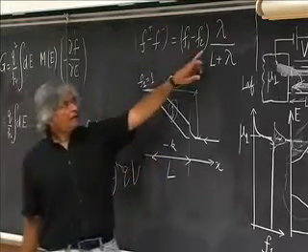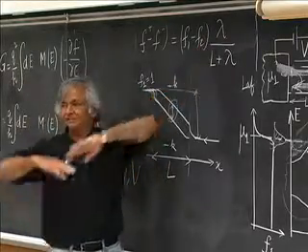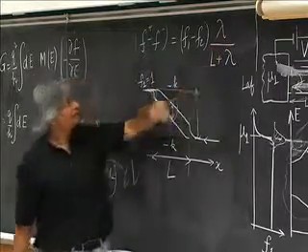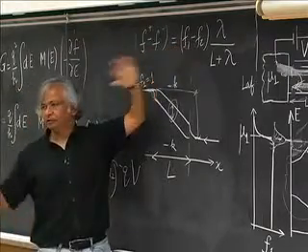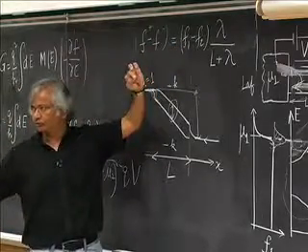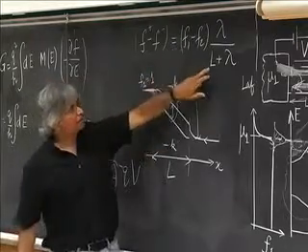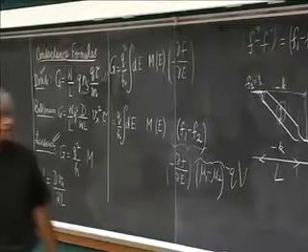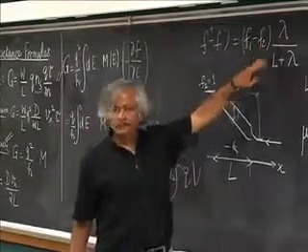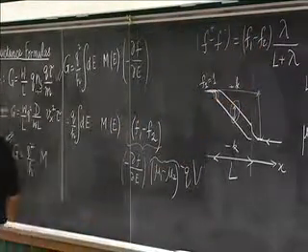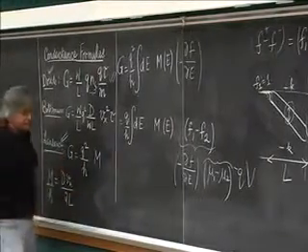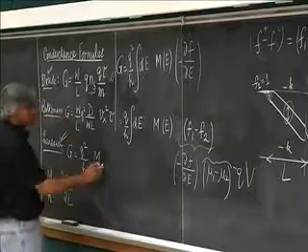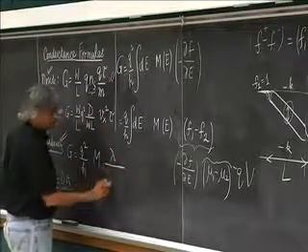So if the mean free path is very long, then that factor is 1 and you have ballistic transport. Then the difference is exactly equal to whatever you have at the ends. That's what we've been talking about so far. But once the length becomes comparable to a mean free path, that's when what you get is a whole lot less. Now the result, of course, is that the current here then, instead of being what I'd written before, is now reduced by lambda over L plus lambda.